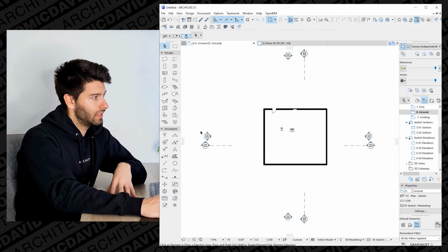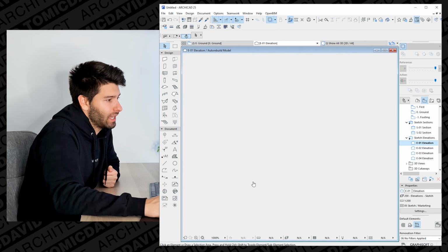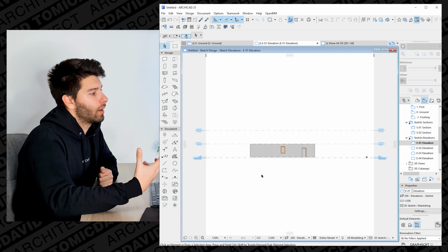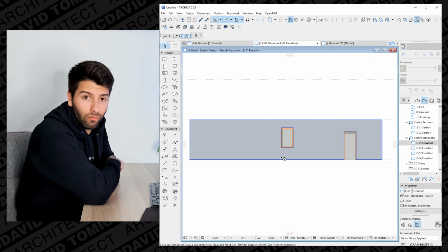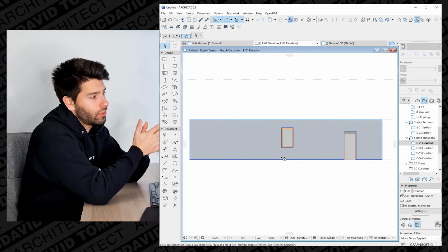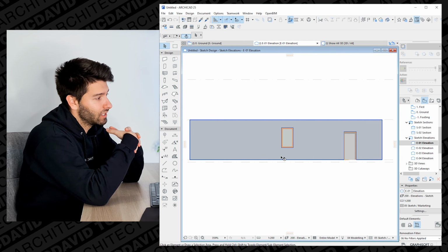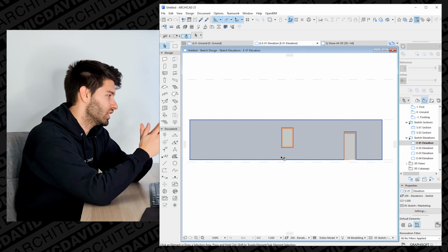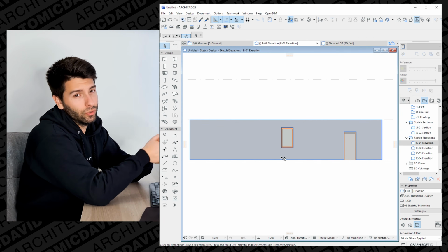So whichever way these arrows point is the elevation we will be looking at. So as an example, let's click E01, it'll open up a new window and it'll show us that elevation of what we've created again in 3D, so we don't have to go back and draw it a million times over, changing every single line, changing every corner, and basically wasting so much time with 2D software.